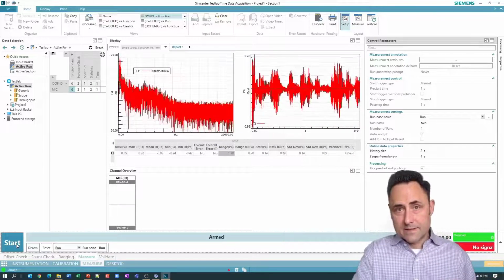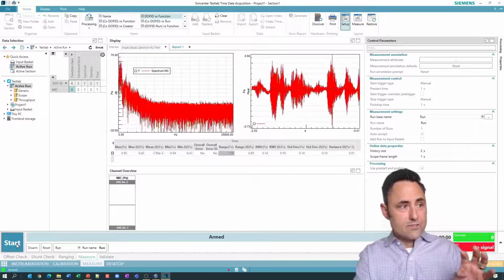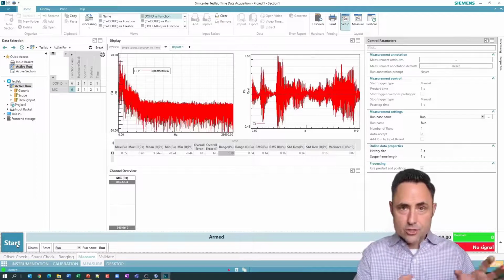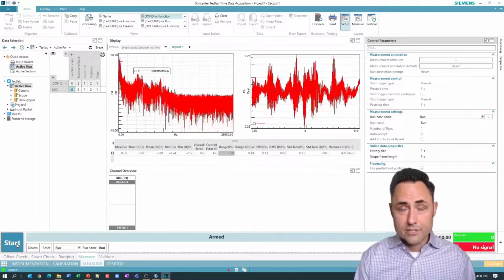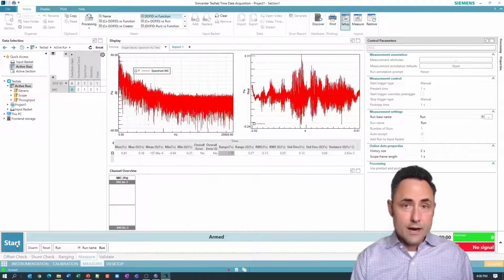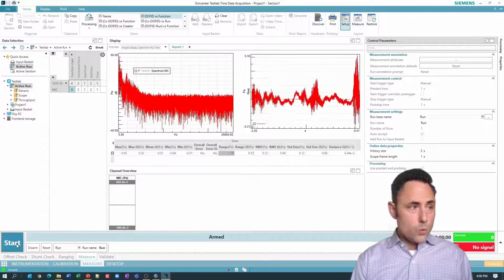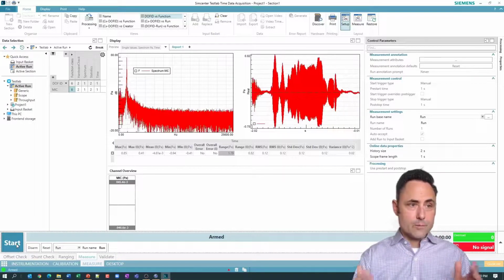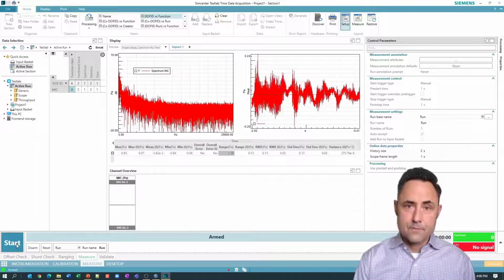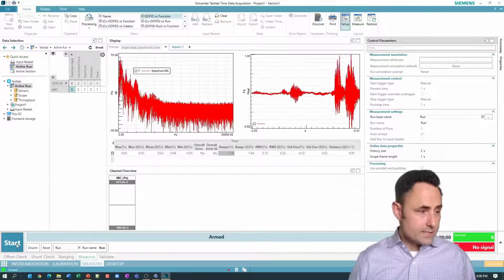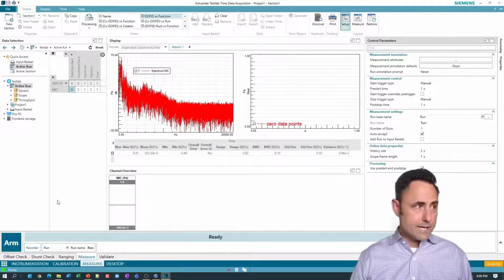It's not processing this FFT in the recorded data that you'll get, but this gives you a live monitor during the test to see what's going on. It's a nice functionality built right into TestLab Neo. Okay, and so you see my whistle, and I get live feedback of that frequency content. So that is setting up the measurement in TestLab Neo.